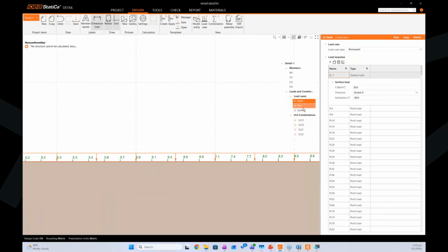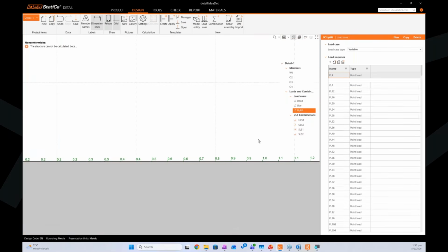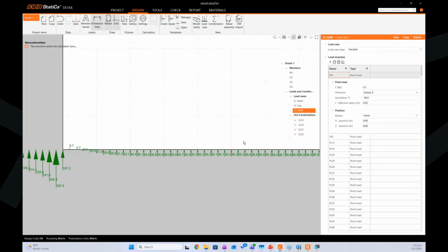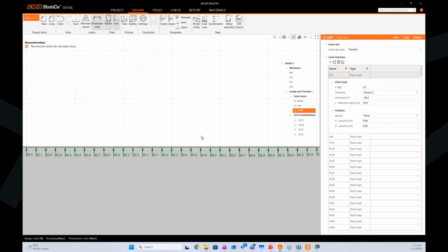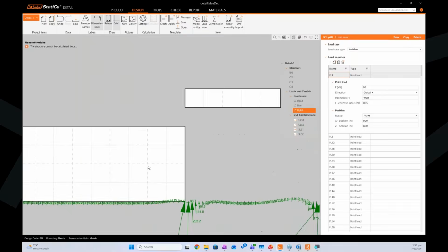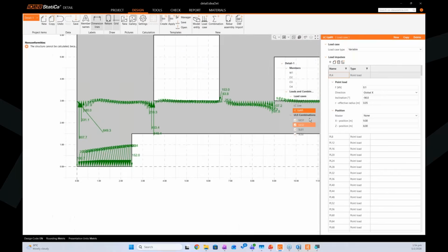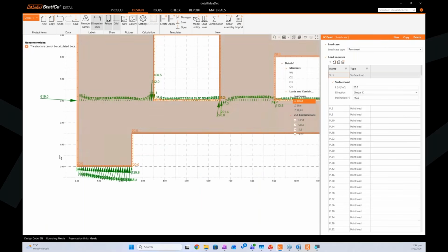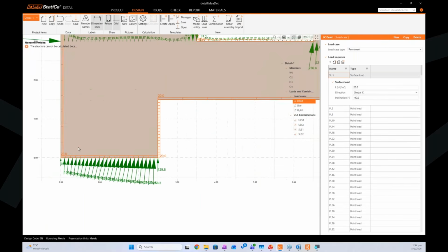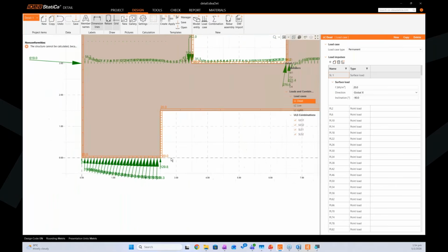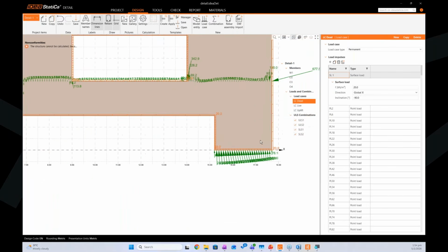Live load as well, and also, as I mentioned, because this is underground, there'll be an uplift force coming from the base slab, the bottom-most slab, as we usually call it. And lastly, there'll be a reaction force coming from the pin, which we had in ETABS.